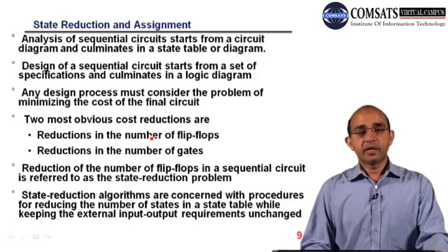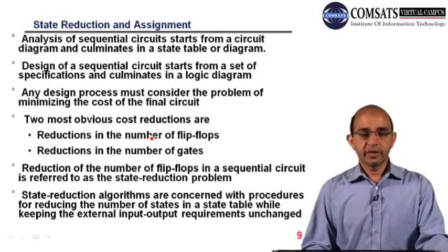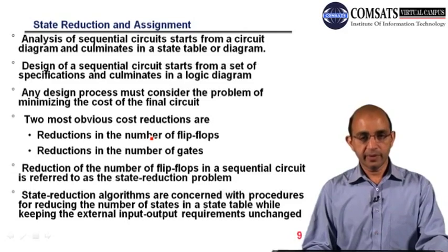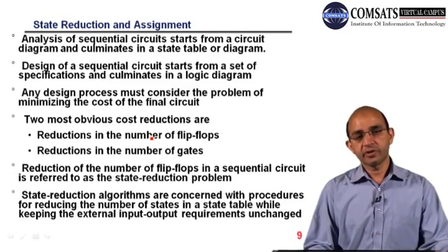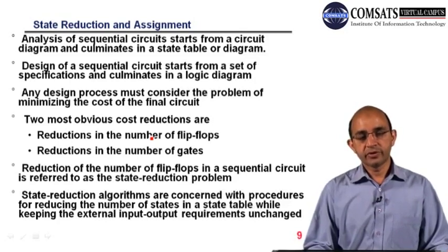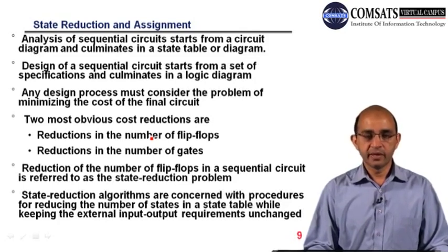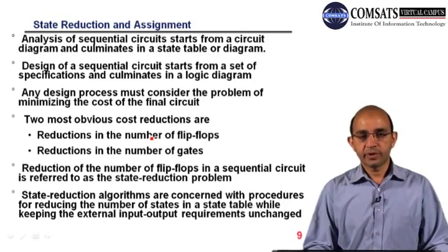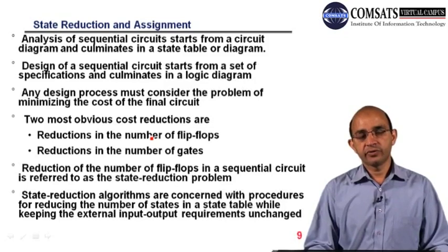Our sequential circuitry is based on the memory element and the combinational logic. Memory elements are based on sequential logic, and the input function or the output function are based on combinational logic. So here our objective is twofold. On the one hand, we want to reduce the number of gates used for the input or for the output. On the other hand, we want to reduce the number of flip-flops.